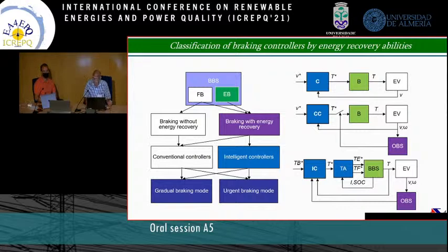To provide more sophisticated control, we usually use the circuit at the bottom right of the slide: an intelligent controller and a torque allocation system, which allocates torque between electrical braking and friction braking, the blended braking system, which implements this control, and next, the electrical vehicle and an observer with commands to our controller.